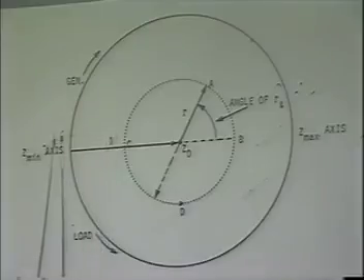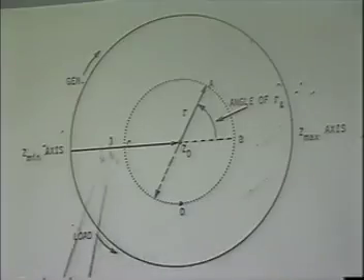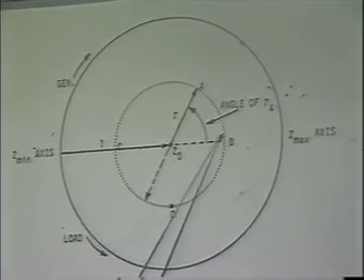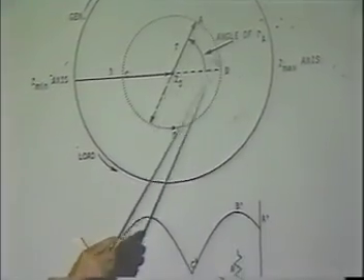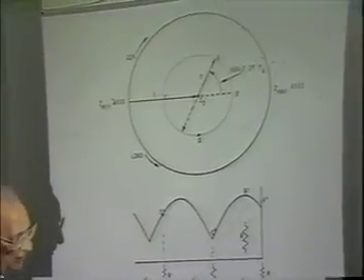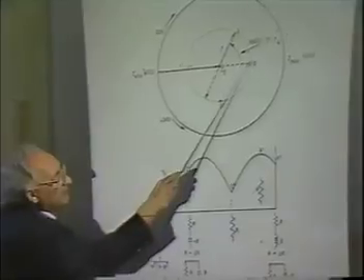Okay? If it's a short circuit, the gamma is 1. If it's anything other than that, in this case we had a gamma of about 0.5, which is the way I drew most of these. So here you go from A to B over here, to Z max, A prime to B prime. On the chart, it's twice the angle of this angle here. You went from an inductive and resistance value to a pure resistance value here.